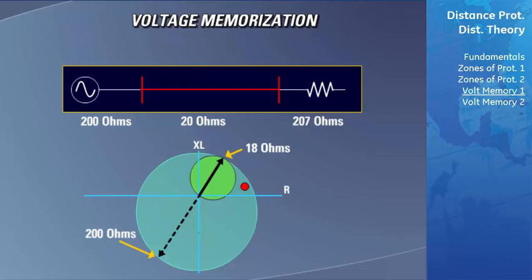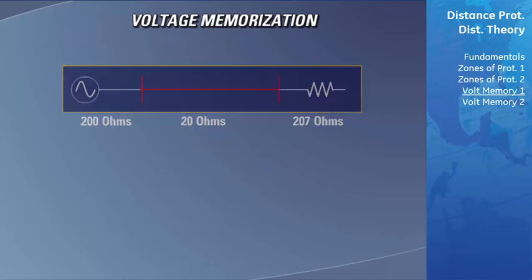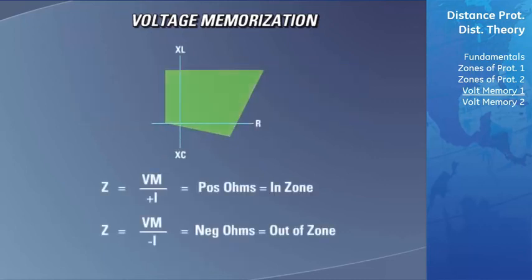Transients of this nature can occur in instances where the 3 poles of a breaker are opening or closing unevenly. If you are protecting a transmission line that is powered by a weak source so that your system will have a very high system impedance ratio, this expansion Mho element should be disabled and a standard Mho characteristic should be used. Another alternative is to use the quadrilateral characteristic where the shape and size of the zone of operation can be customized to fit your needs.